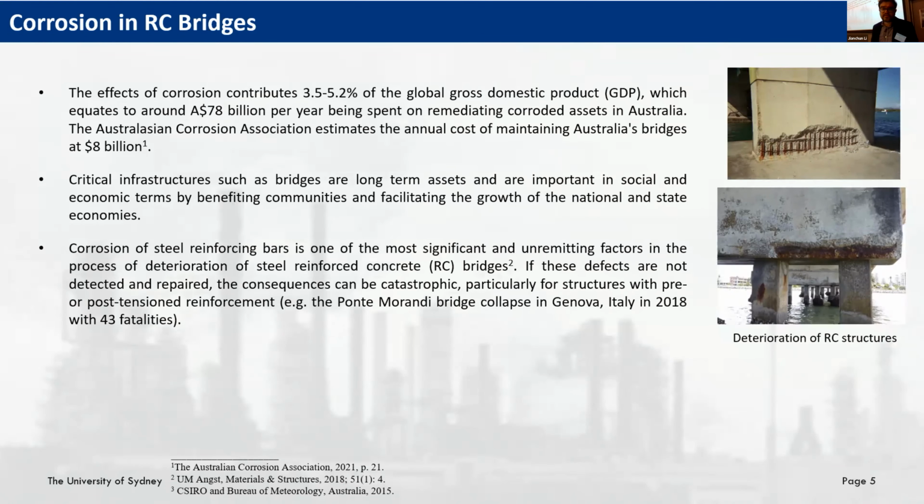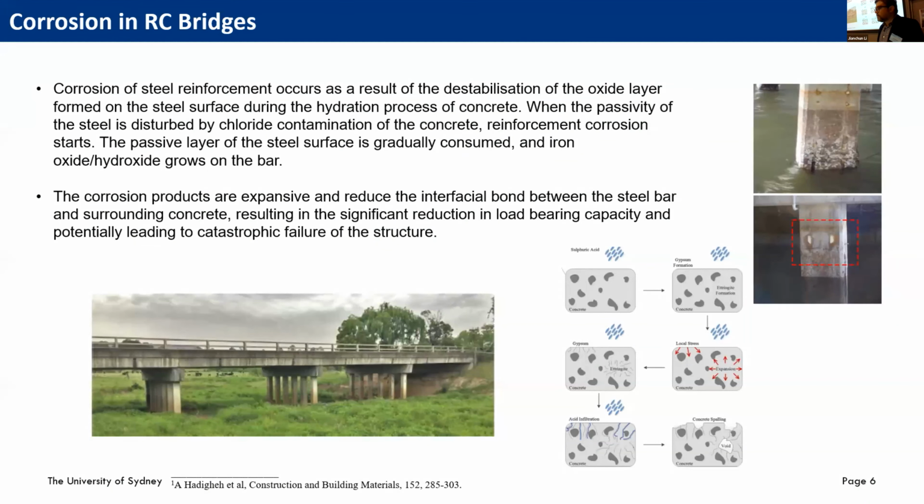That is causing a lot of issues specifically for reinforced concrete bridges, because corrosion usually occurs very easily in marine environments because of carbonation or acidification of the mortar and diffusion of chloride ions into the system, basically damaging the passive oxide layer on the rebar, and oxidizing the rebar, and initiating corrosion.